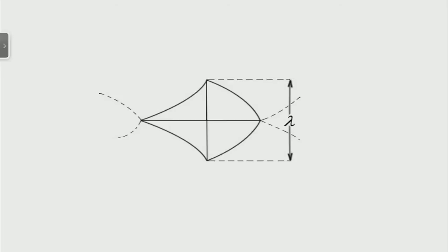Let us take one more look at this particular cell. You have the triple point coming along this trajectory, you have another triple point coming along this trajectory, you have transverse waves over here, the transverse waves intersect over here, it starts a Mach stem shock, it comes over here, it decays in strength, becomes an incident shock wave, and then the writing of the triple point is along this trajectory. The triple point and the corresponding transverse waves intersect here, another cell is born over here, and this is the way from cell to cell the detonation wave propagates.